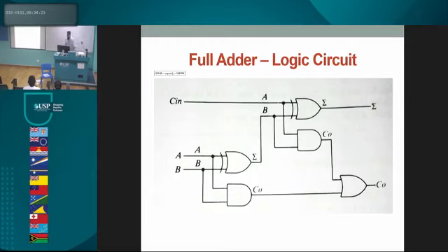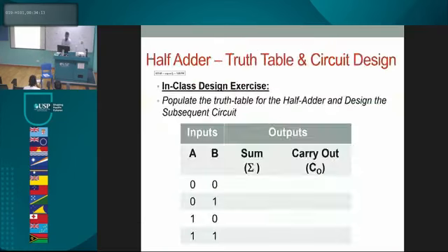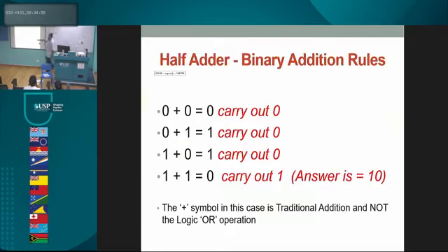Look at this circuit. Where did we start off from? We started off from just the baby, just a little XOR gate with an AND gate, and this was only to cater for this much. That circuit can do this very neatly, the second line very neatly, the third line very neatly. In the final line, the sum is 0 and the carry out is 1. So it was able to handle that.